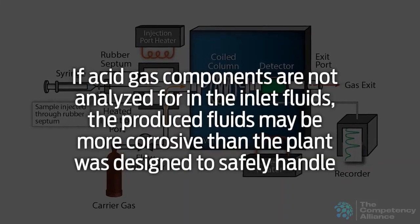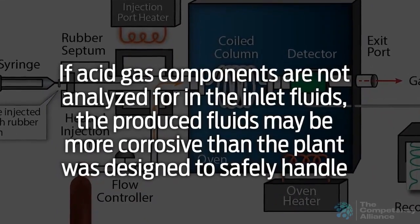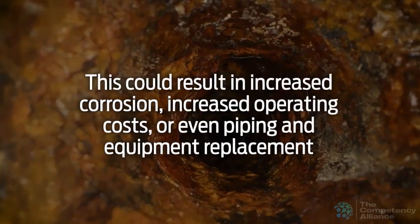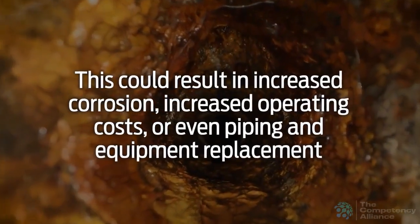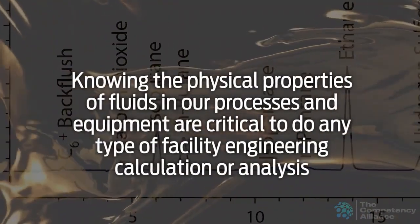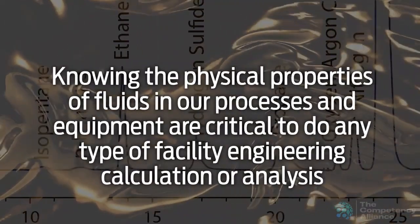If acid gas components are not analyzed for in the inlet fluids, then it may be possible that the produced fluids, which are water wet, are more corrosive than the metallurgy of the plant was designed to safely handle. This could result in increased corrosion, increased operating costs due to needing to add corrosion inhibitor, or even piping and equipment replacement. Knowing the physical properties of fluids in our processes and equipment is critical to doing any type of facility engineering calculation or analysis.